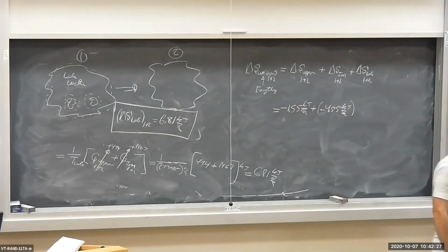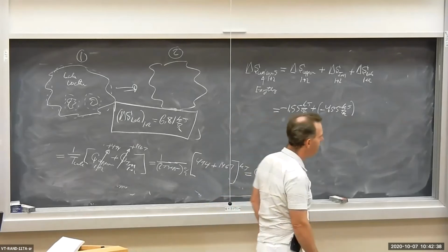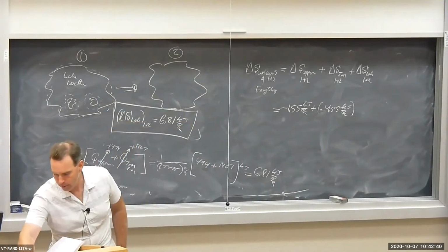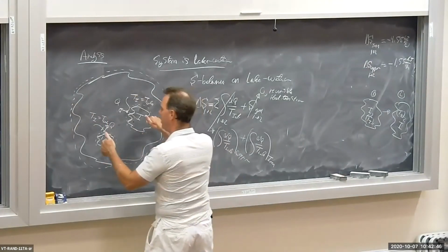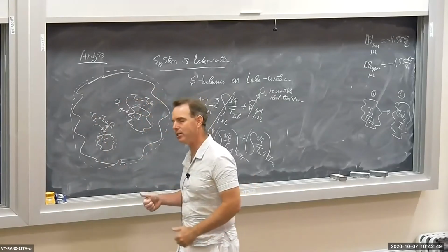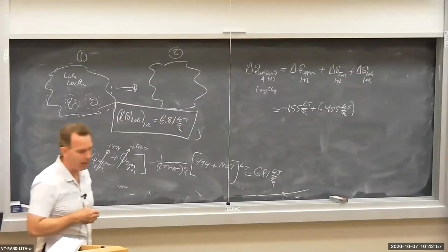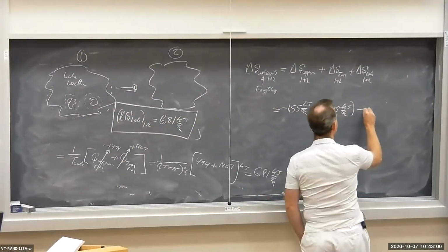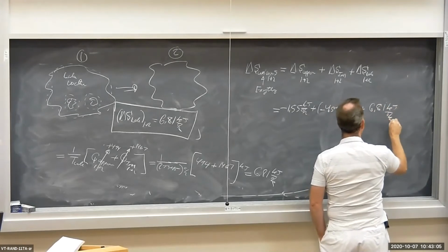The lump of iron cooled down, so heat was transferred out of the iron, as well as entropy, so entropy fell for the iron. But the lake gains entropy because heat's being transferred from the lumps of copper and iron into the lake water. So the lake is gaining entropy and energy due to heat transfer from the iron and the copper as they cool down. So then I got a plus 6.81 kilojoule per degree Kelvin.